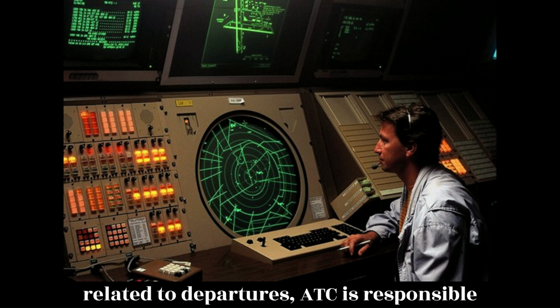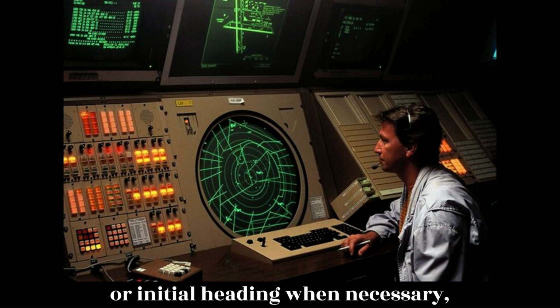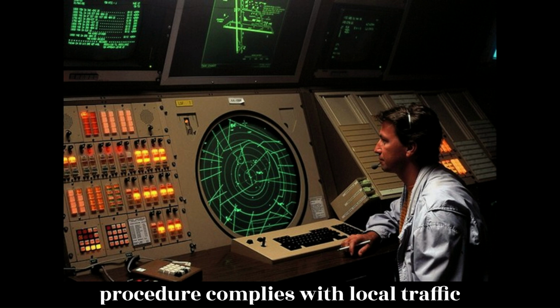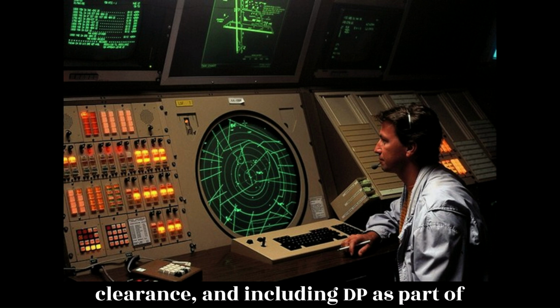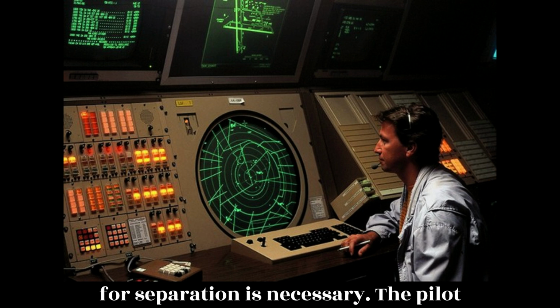Specifically related to departures, ATC is responsible for specifying the direction of takeoff or initial heading when necessary, obtaining pilot concurrence that the procedure complies with local traffic patterns, terrain, and obstruction clearance, and including DP as part of the ATC clearance when pilot compliance for separation is necessary.